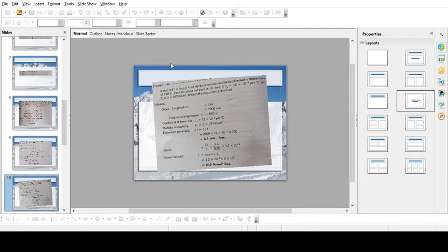The bottommost bar will expand freely to its maximum point of expansion, whereas the upper part will not expand completely, because the stresses induced in the bottommost part act as a compressive load for the topmost part.